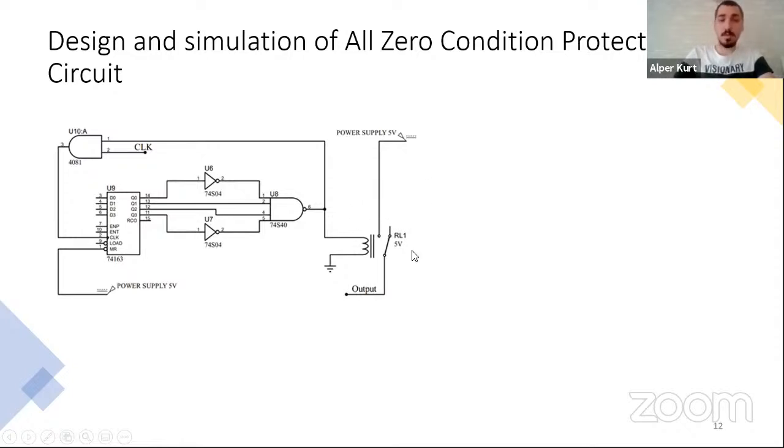By doing that, one of the nodes, since I will connect this node to any part of the LFSR, will become 1 instead of 0. So it ensures that the all zero condition never occurs. At the same time, since this node is 1, I apply the clock with 1 to the AND gate and the output of the AND gate to the binary counter. Since here is 1, the output will become the clock, and the clock is applied to the binary counter.